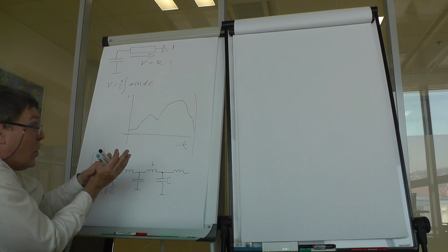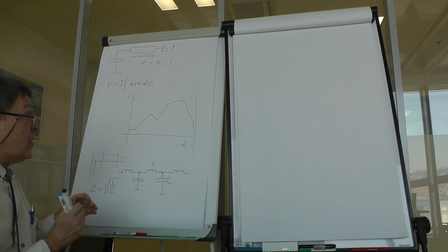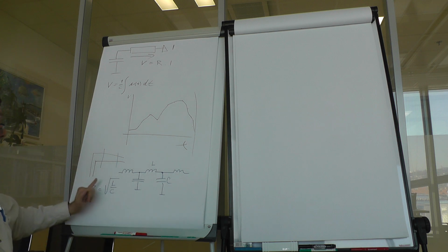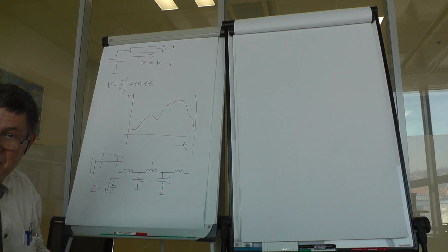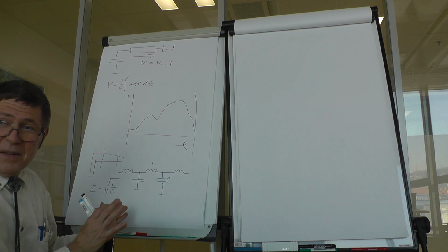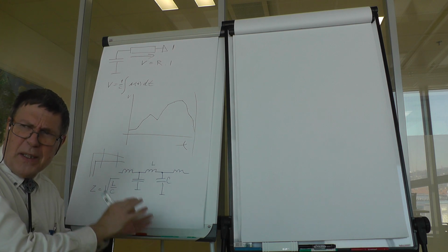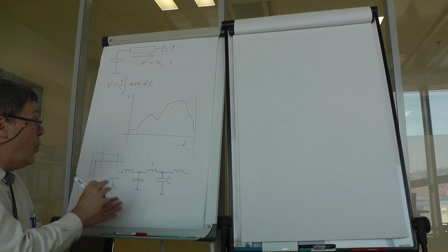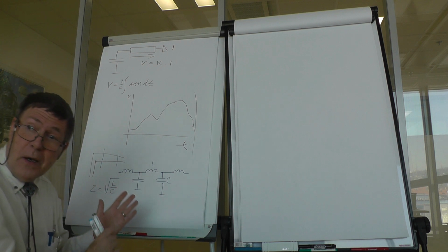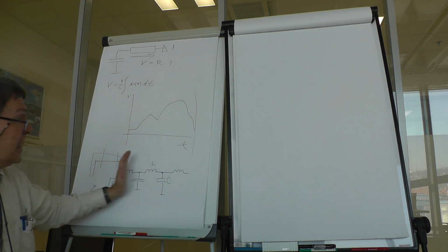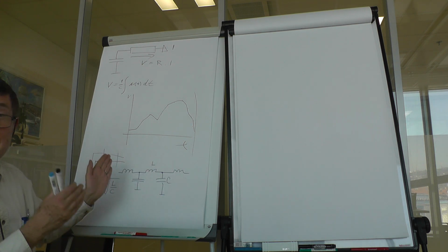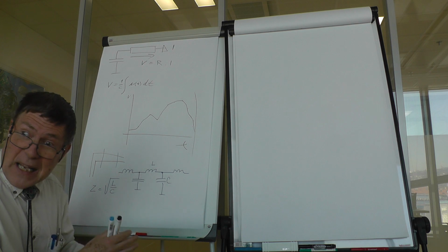So this is a low-pass circuit, which then would mean that this nice equation for the impedance in circuit theory, exactly called image impedance, would hold to more or less 1/2 of the critical frequency, that is the end of the passband.